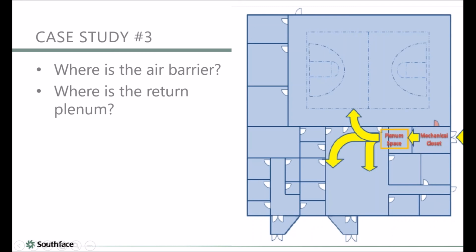So basically you had this easy pathway for outside air to come in here, and then there was no barrier, no separation. Yeah. So that outside air just comes in, and then it gets into the space that's effectively a return plenum. So it's drawn in by the return, lack of return ducts and so on. So no clear air barrier, no clear return pathway, and faith-based ventilation.